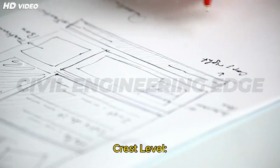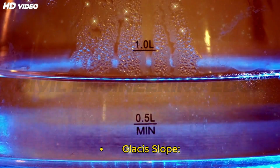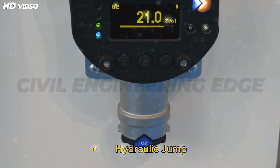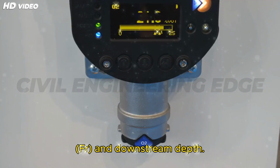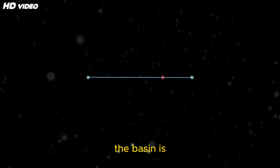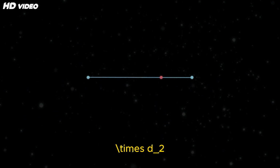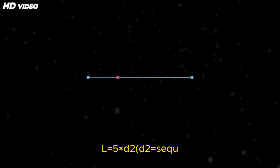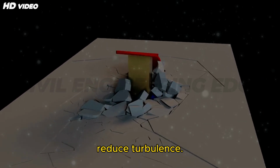Design elements: crest level, positioned slightly higher than the downstream bed. Glacis slope, typically between 1 to 2 to 1 to 3 V/H depending on flow rate. Hydraulic jump location, calculated based on Froude number Fr and downstream depth. Stilling basin and baffle blocks. The length of the basin is generally L equals 5 times D2, where D2 equals sequent depth. Baffle blocks are placed to stabilize the jump and reduce turbulence.